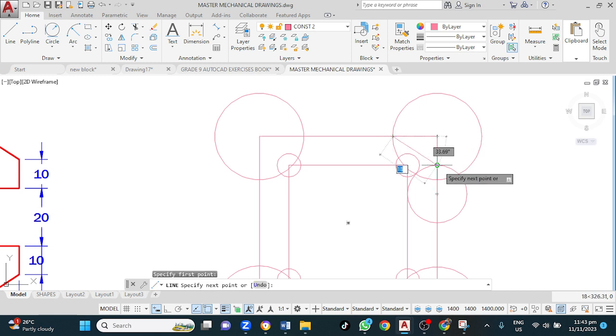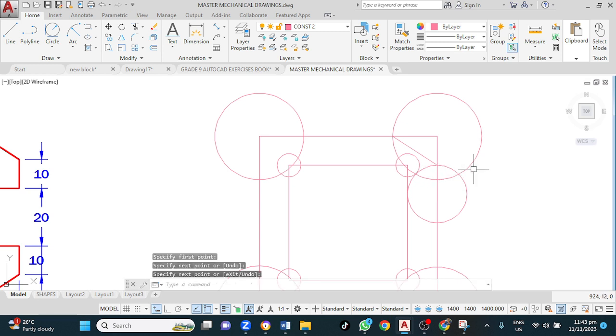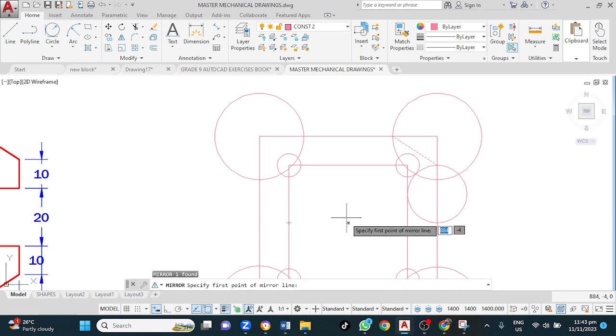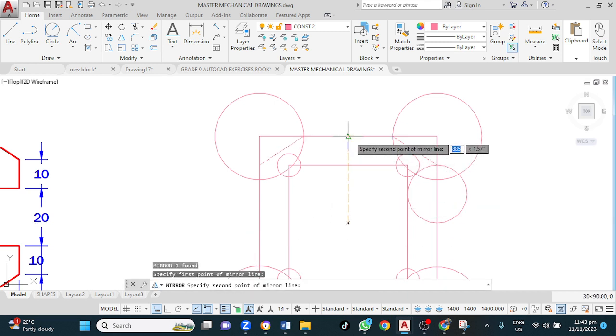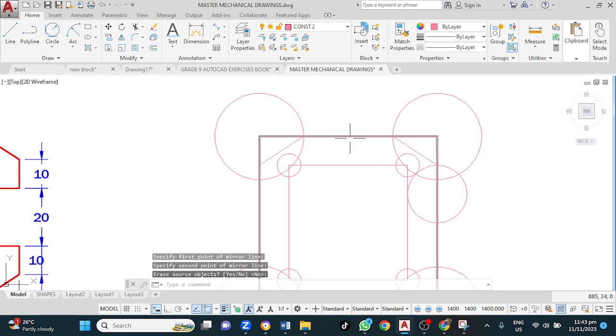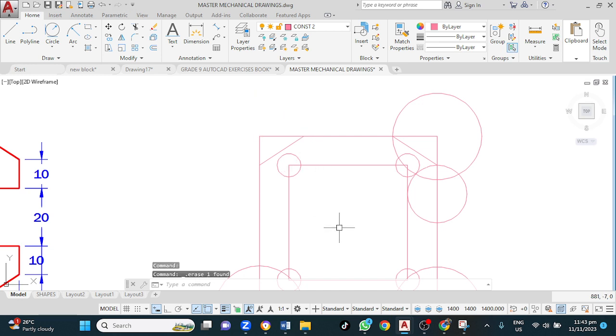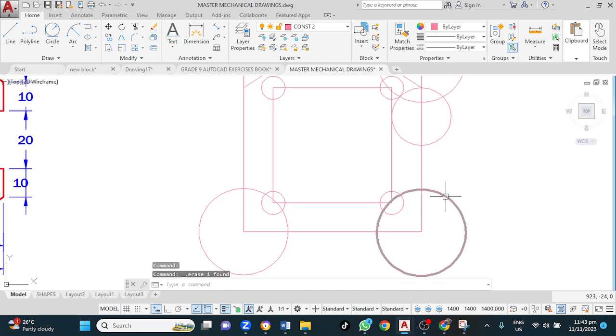In a case like this, you probably don't need to do more than one, and then mirror it, right? Left click here, MI for mirror, enter. So it's basically a waste of time drawing all of those. Join all of these, you don't really need them. Mirror will take care of that, and we're gonna mirror both of them down here.